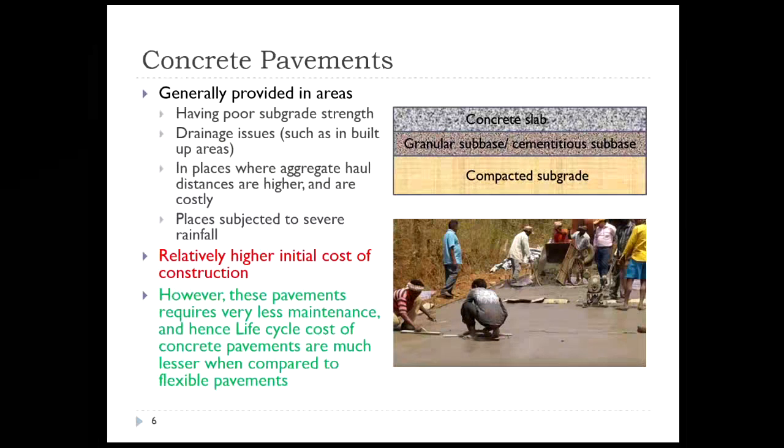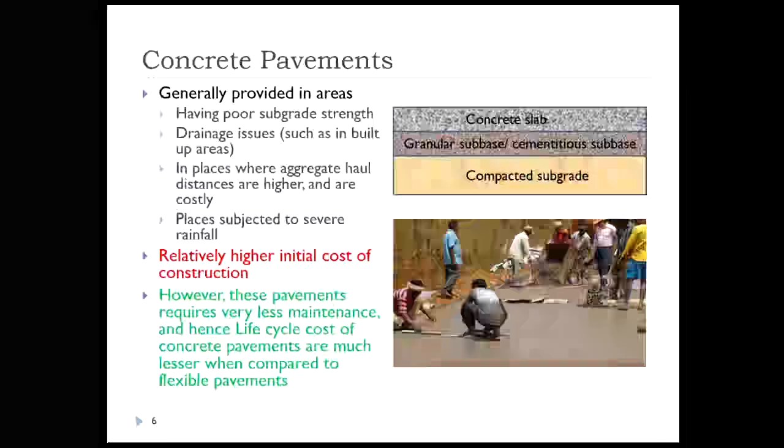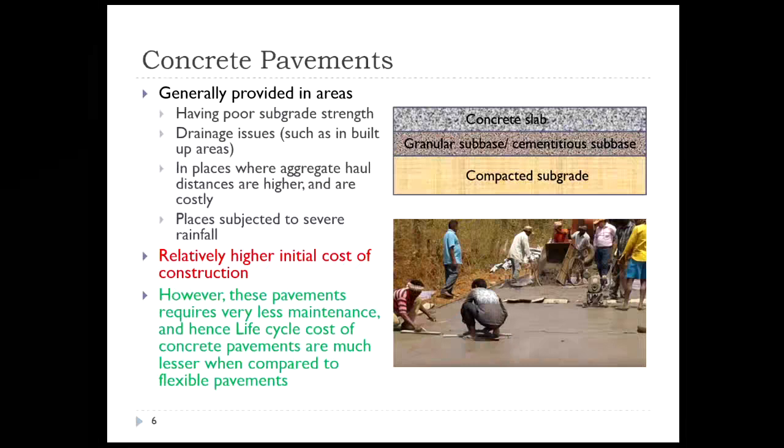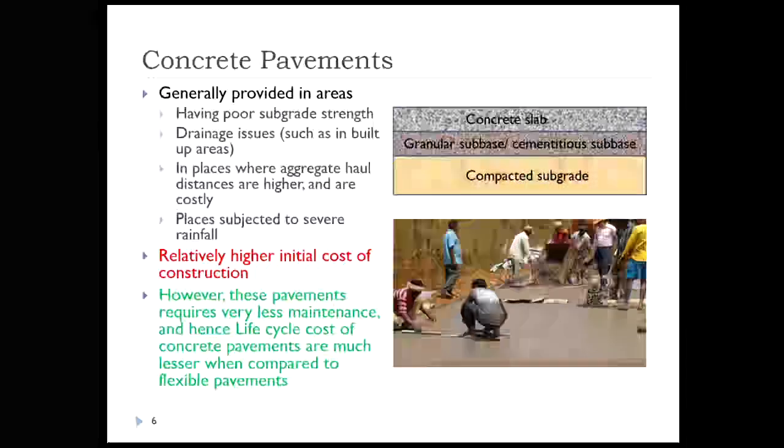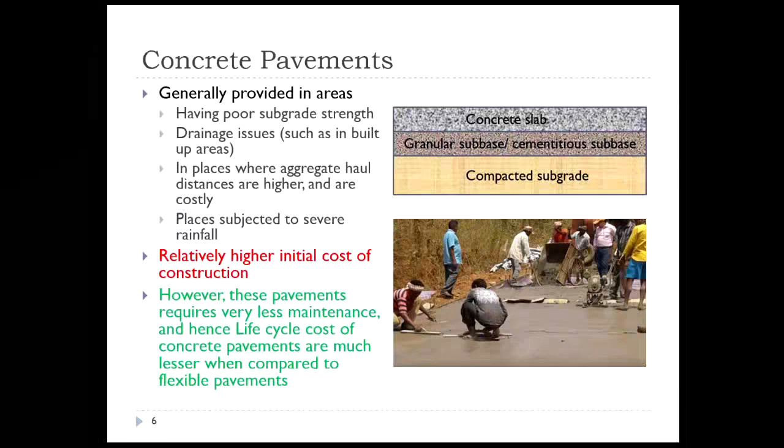Okay. Now, one of the major advantages of concrete pavement is that even if the slab breaks, even if the slab undergoes cracking, unless the portion starts falling off, the drivers will not find discomfort while traveling on the concrete pavement. Whereas in the case of flexible pavements, once a crack initiates, the bituminous surface disintegrates into smaller aggregate chips, and it will result in much discomfort for the passengers. So this problem we don't have in the case of concrete slab.